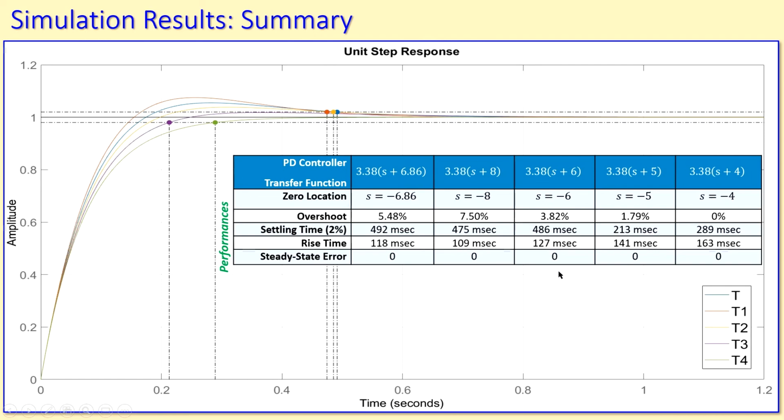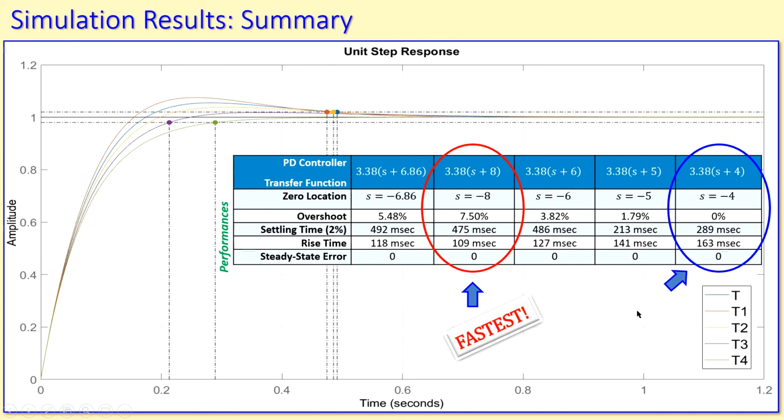And to meet all of the specifications, also including the deadbeat response table, we have the following situation. So this is what you have for the fastest rise time. This is the fastest response. But this system in the last column will produce the required situation for our deadbeat response table. And it is below the 0.5 seconds settling time, which is the maximum allowed for this situation. So that's fine. So that's the conclusion for our analysis in this case, using the deadbeat response design to design a PD controller.